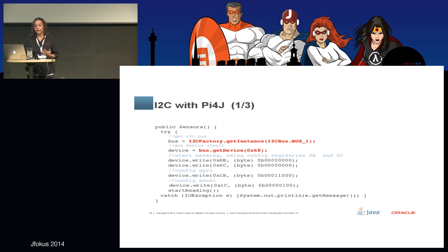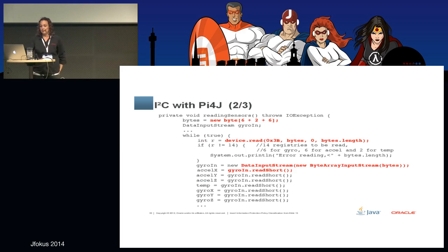So that's what I'm doing in the next 2 lines, setting the sensibility of the gyroscope and accelerometer. Do not ask me what these values are for. I do not remember. But again, the document will tell you this bit is for this, this bit is for that. So these are the values that work for my particular case.